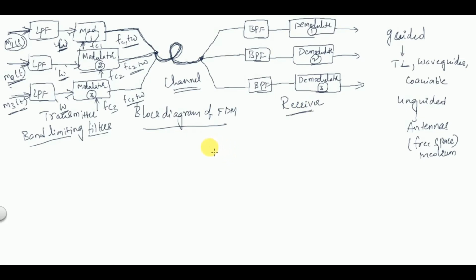So this is the process where we have different frequencies for different signals. The same concept is used for cable wire. In the cable wire we transmit video signals of different channels through the same cable. All the signals are video signals with the same frequency range, but using different carrier frequencies we can tune to different frequency ranges for the signal.